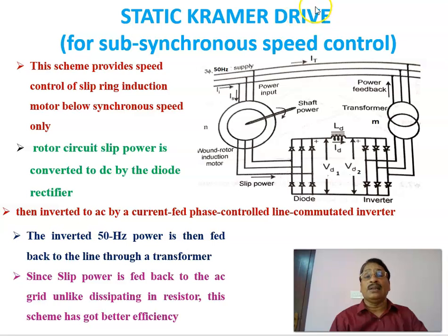Static Kramer drive system is used for the speed control of slip ring induction motor less than the synchronous speed, or for subsynchronous speed control. Therefore, this scheme provides speed control of slip ring induction motor below the synchronous speed.